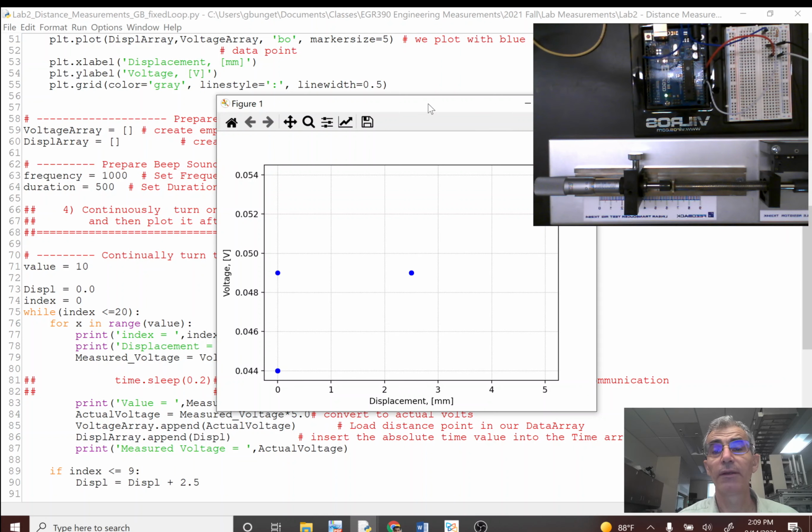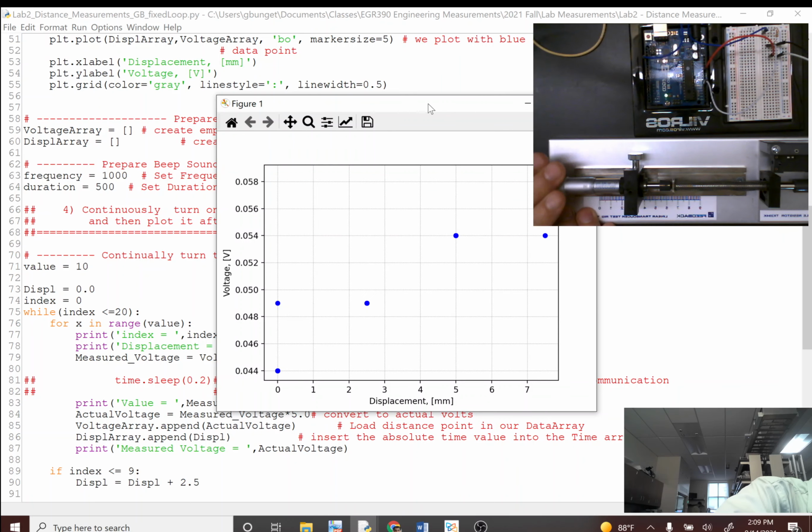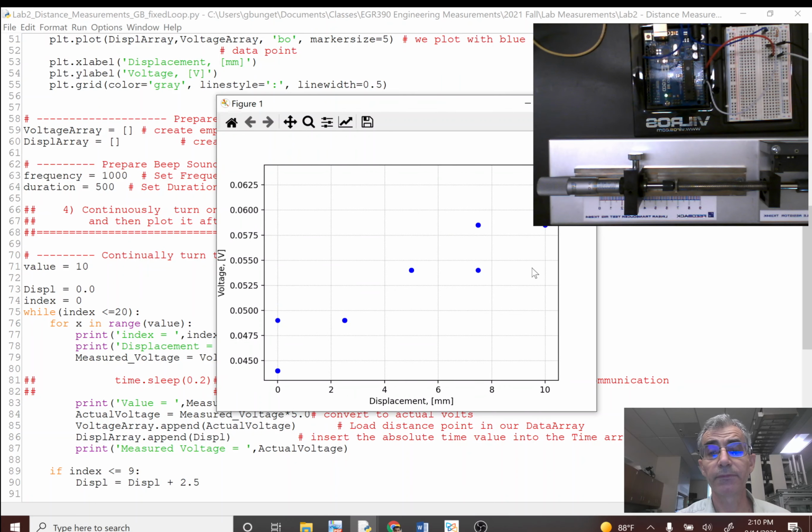Got the measurements, as we can see, I get some errors. Not all the 10 points are in the same location. I have some of them right here and others there, so it appears that it's a linear curve, but with some errors, like this one. So this potentiometer has some low accuracy.